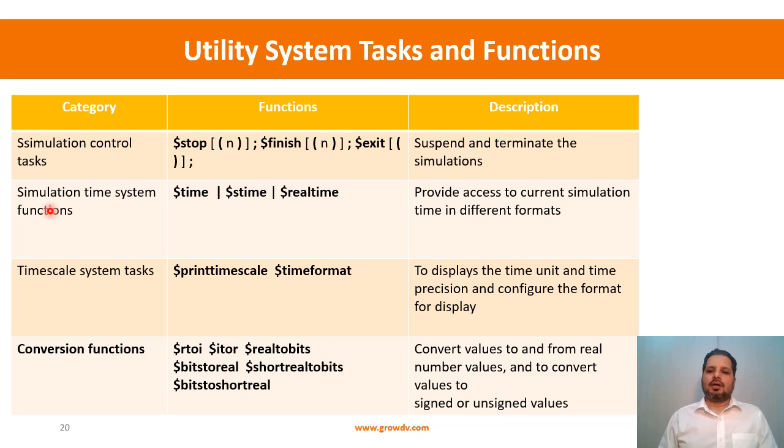Then you have the simulation time system functions. You have $time, $stime, $realtime, which provide access to the current simulation time in different formats. And then you have the timescale system functions, wherein $printtimescale will print the time unit and the time precision. And using $timeformat, you can configure how these simulation time system functions will display the time information within the simulation log.